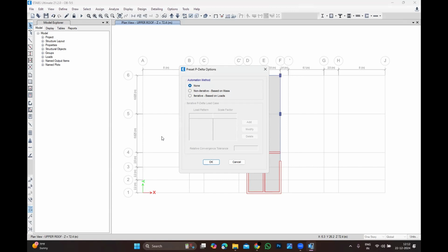When you are applying lateral force, and obviously you do have lateral force, I'm not talking about only seismic, wind is also lateral force. Very important, the P delta concept is: when you do have a lateral force, in any buildings, even industrial structures, whatsoever it is, the structure will sway. If you don't have lateral force, you don't have any sway. As it is. Okay.